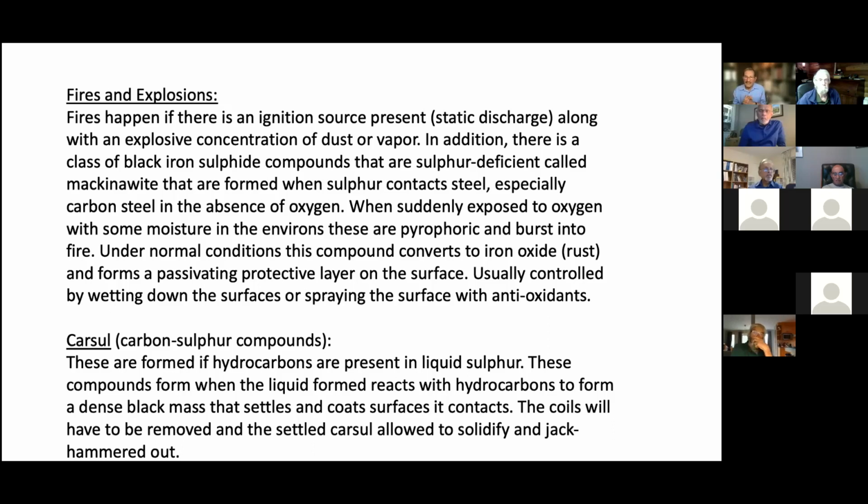That's why in remelting sulfur, if you're dealing with contaminated sulfur, you want to avoid as far as possible any heating coils that are exposed to the liquid sulfur itself. You want to jacket it. You want to use other methods that we can discuss later on. Otherwise, what happens is they get coated and you lose the heating effect.